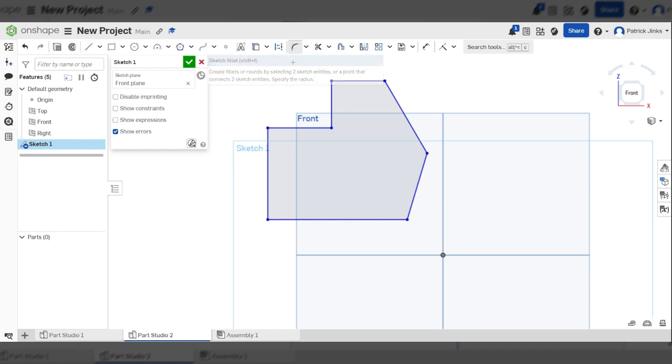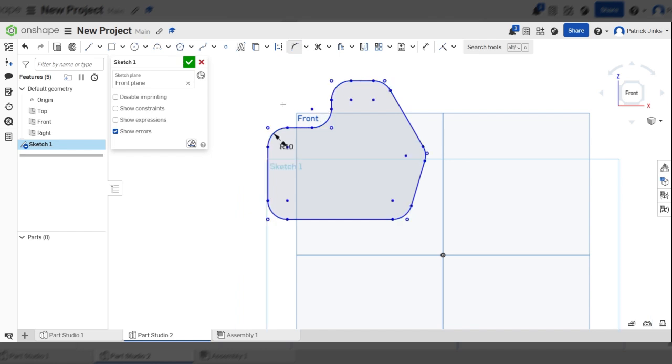All you're going to do is click that and then click on every corner. You don't have to. And again, if I'm clicking on every corner, I could have just clicked and dragged around the whole shape. Now, when we do this, you will get one icon here. That is the radius. And we can either pull all the curves in, or I can double click and set a dimension on this. So I'm going to set it to 10. Press enter, and you will see now I've got a 10mm radius on all of those corners.